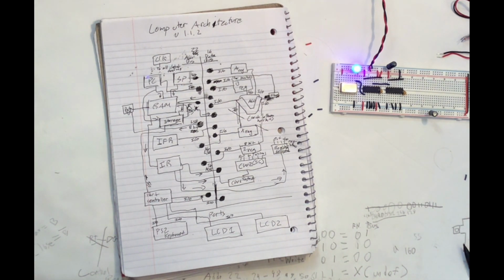And then the final port would be the interval timer, and I'll actually talk about this and how it will work. So it will be able to set a time, and it will count down and give an interrupt to the system, and then it will be checked and handled. And if you want to have multiple delays from different programs, you can do that by just doing the subtraction, and then after the first delay goes off, the next one would be immediately put in by the operating system, getting fairly good delays.